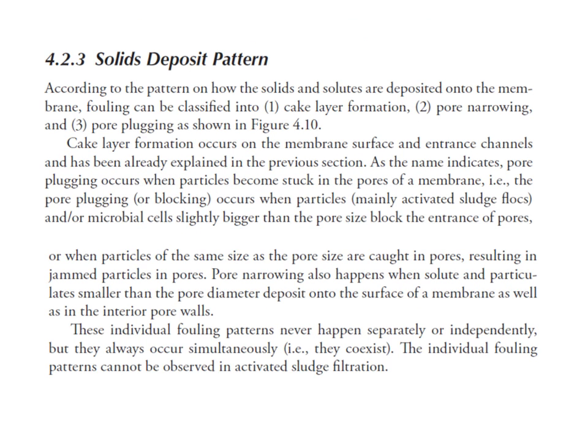If you compare the solid deposit patterns, there are actually three typical types that we can generally observe in the membrane process. The first one is the cake layer formation. The second one is pore narrowing, and the third one is pore plugging.